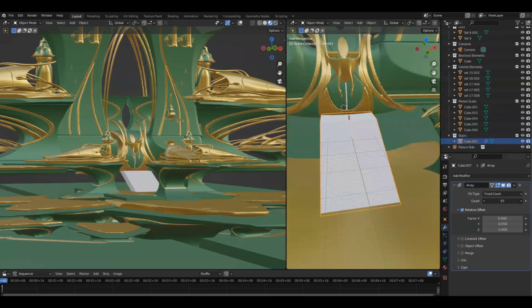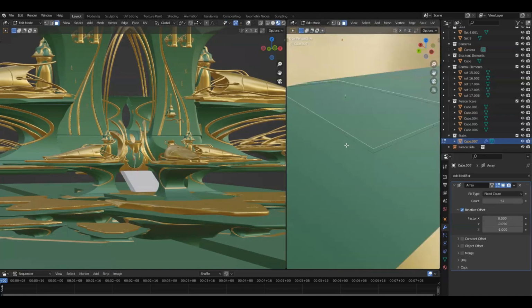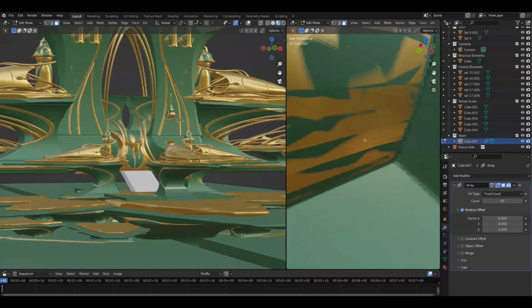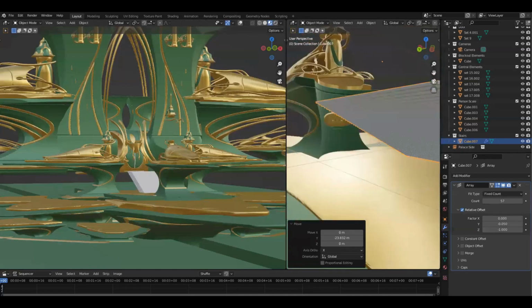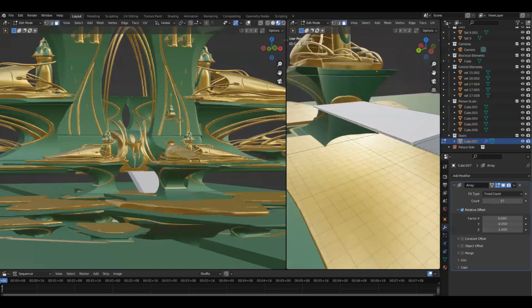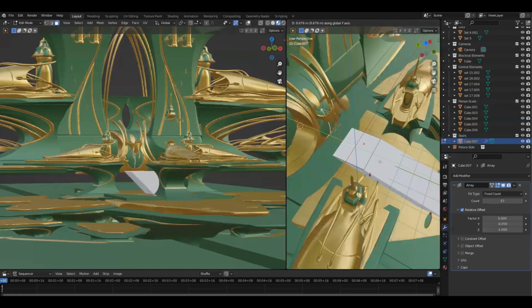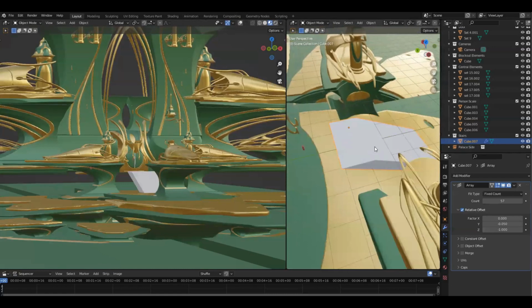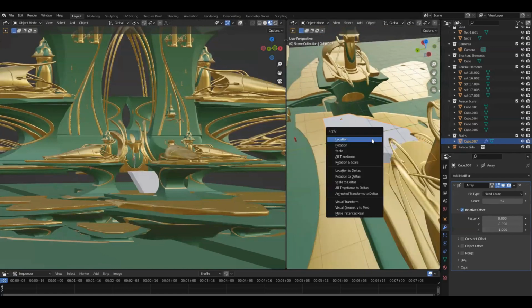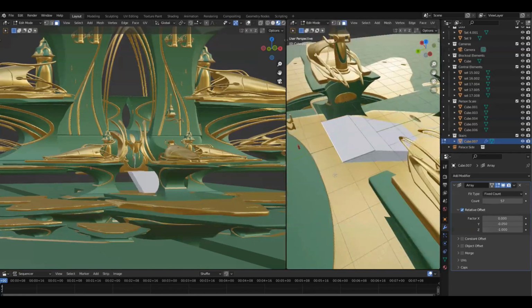And I'm just actually going to go ahead and edit this plane so we don't have to add too many more objects here. So just want to select this back face really quick. Actually, let's move it out so I can easily grab it. And I'm thinking if I just push this segment, why is that adjusting everything? It's kind of getting some interesting stretching when I think it shouldn't. So I think what we need to do is actually Control A on object mode and apply all transforms. Nope, that didn't solve it.